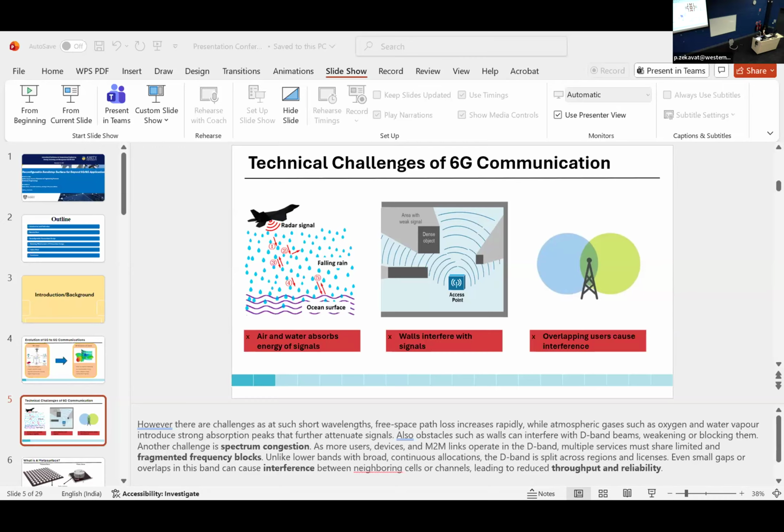This last study introduces a reconfigurable metasurface as well, where the stop band is shifted across different spectrums using PIN diodes. The design is based on a rectangular loop meta-atom where the diode biasing dynamically adjusts the stop band frequency.